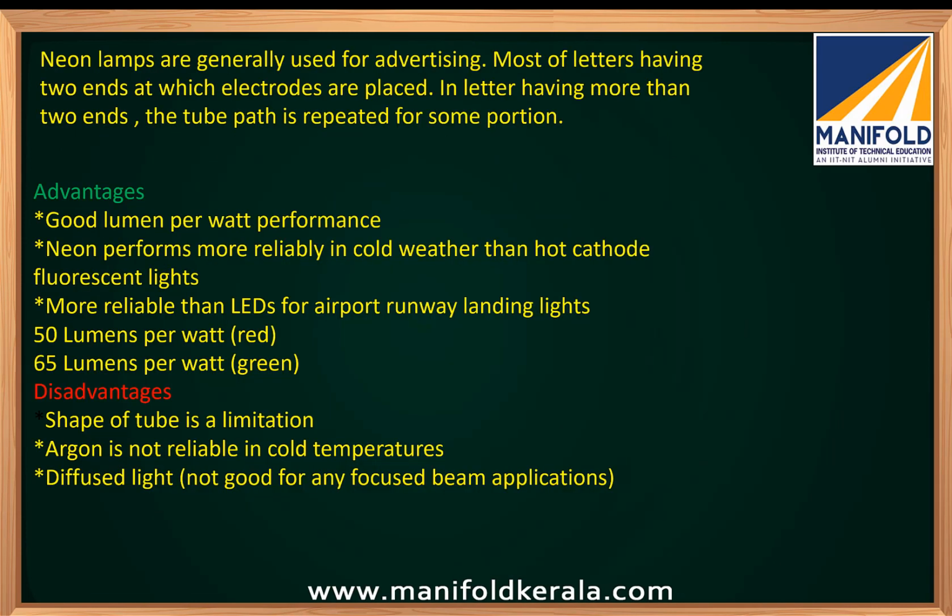Neon lamps are generally used for advertising. Most of the letters have two ends at which the electrodes are placed. In a letter having more than two ends, the tube path is repeated for some portion. Advantages: good lumen per watt performance. Neon performs more reliably in cold weather conditions than hot cathode fluorescent lamps. More reliable than LEDs for airport runway landing. 50 lumen per watt in red color, 65 lumens per watt in green color.